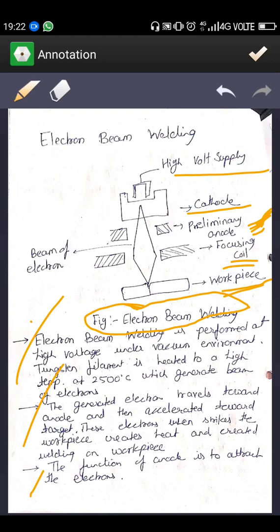Electron beam welding is a focusing process where fast moving electrons hit the metal surface, which transfers the kinetic energy of the electrons into thermal energy. This energy can be used to melt and fuse the targeted material. If this process is carried out at the junction of two metal plates which are to be welded, the fusion causes welding.